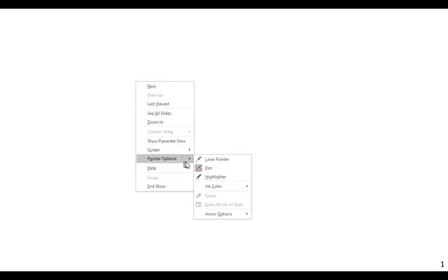Okay, so let us consider similitude. This is in 7.8 and 7.6 of the Munson text. I want to describe the need and benefits of similitude in fluid mechanics, describe the common variables and dimensionless groups used for creating models, and finally apply the principles of modeling and similitude.